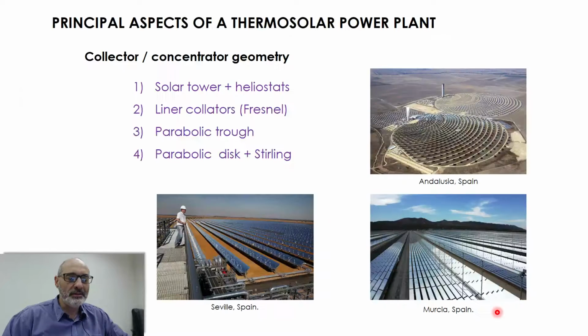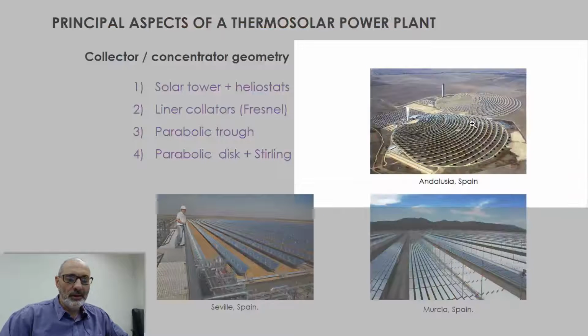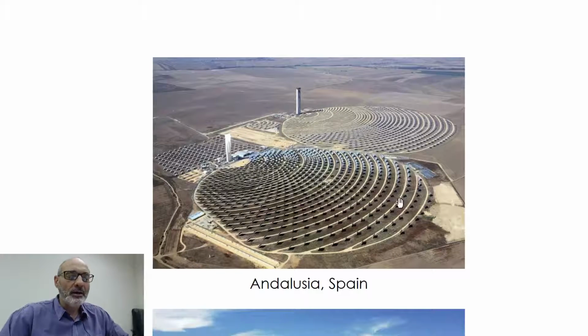They are sensitive to aeroelastic effects. I'm going back some slides just to explain this here, at our solar tower. What happens is that these mirrors start to vibrate because of wind, for instance, the action of the wind makes them vibrate and deform.